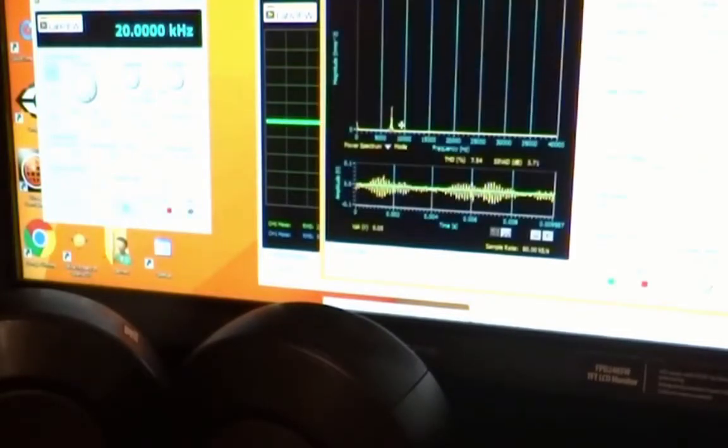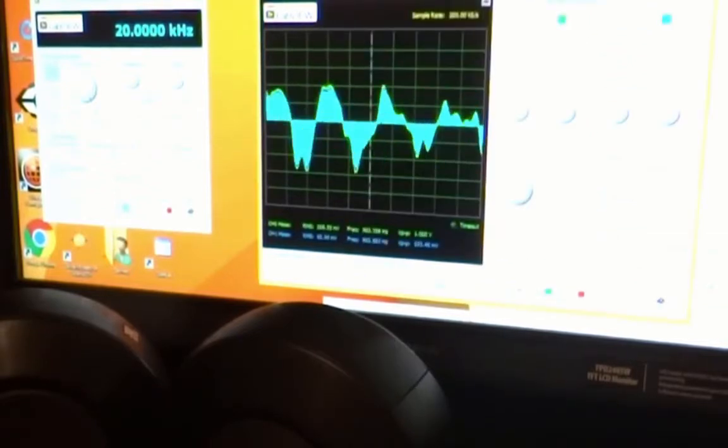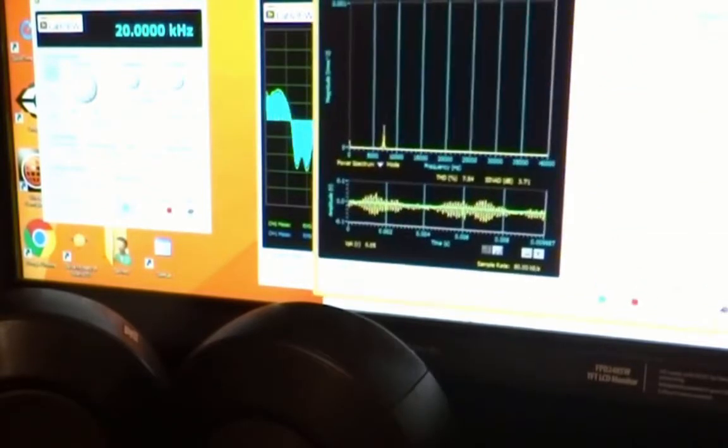So, to get a handle on this, let's go back to the frequency analyzer. And now we can see why I wanted to put this up at 40 kilohertz instead of down at 20 kilohertz, which would really be all we would need for most human audible audio. So let me restart that again. Oh wait, need to stop the scope, need to start the spectrum analyzer.